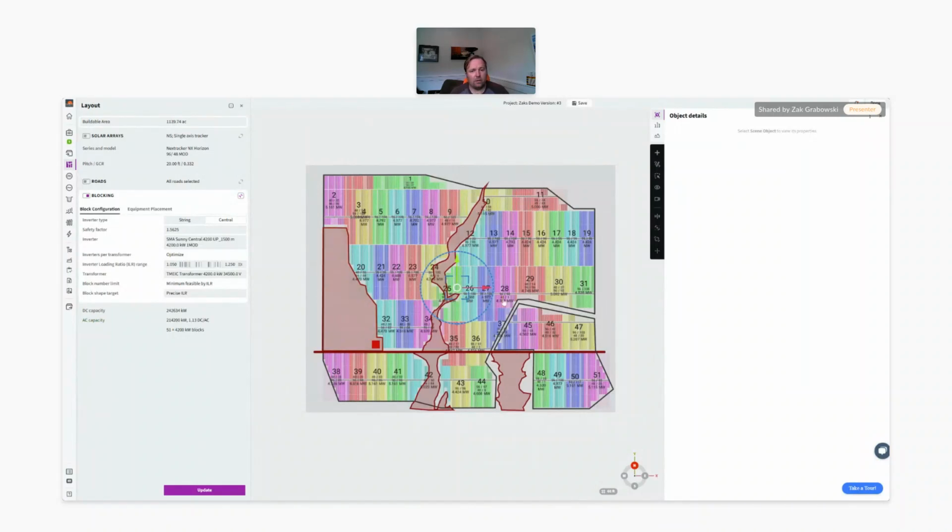And then you can do all the things we're doing in PVFARM with a layout that wasn't necessarily created in PVFARM. So you can see it reallocated down to 51 blocks, and you can see our blocks in general obviously have gotten bigger because we now have a bigger transformer. So really within PVFARM, we have the option to use it to create our layouts from scratch. We can bring in layouts, we can run analysis, and then we can export out those items as well.